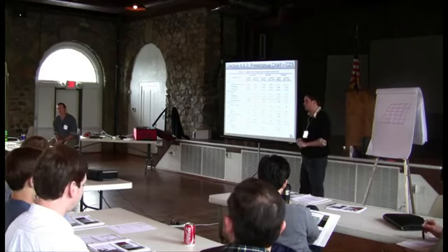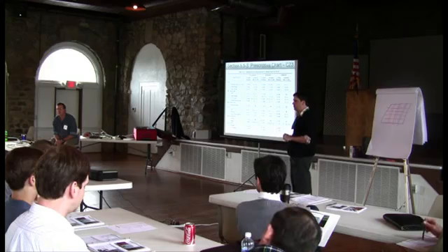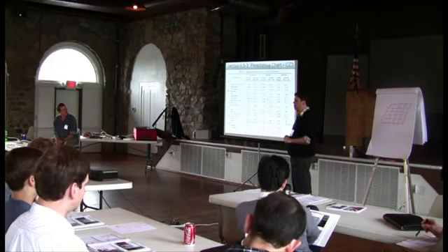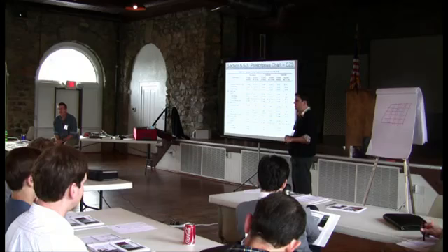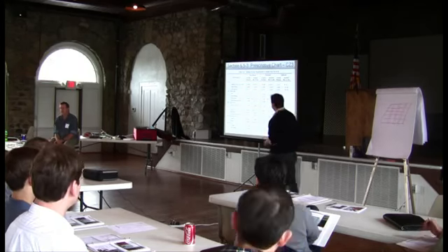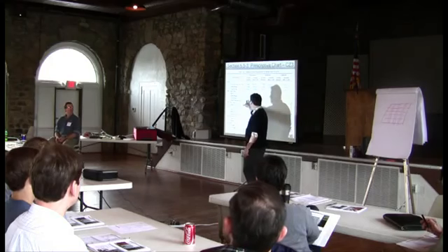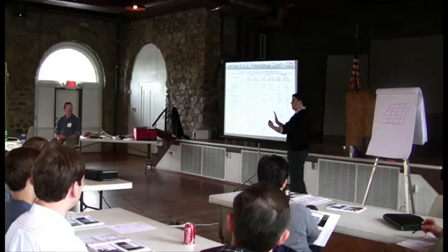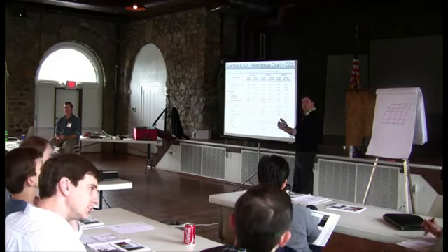Sorry. I'm not sure if you did or not. The steel frame where it says R13 plus R3.8, do you have to have two separate insulations? Not necessarily, though. You've got this U factor of 0.084. You actually could do all exterior insulation. Correct.